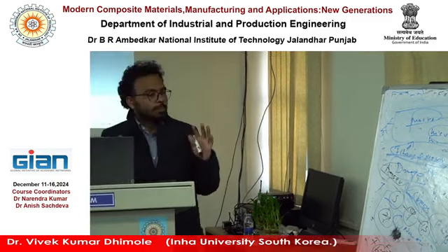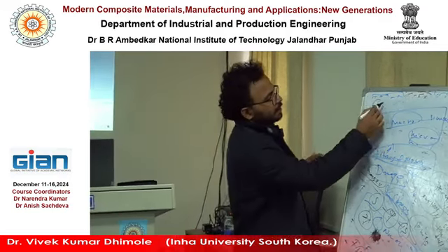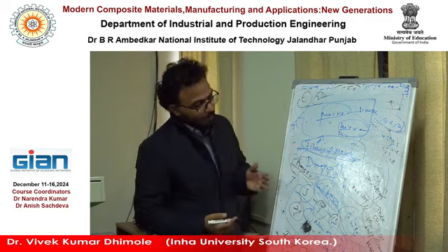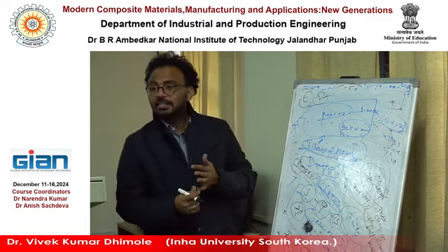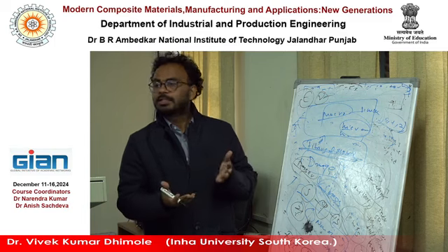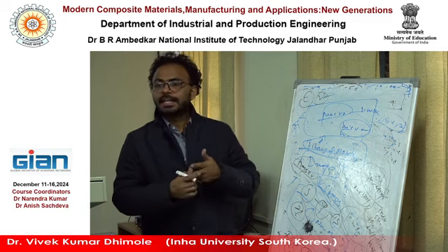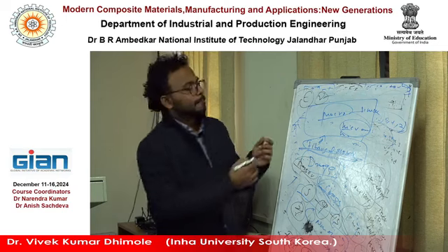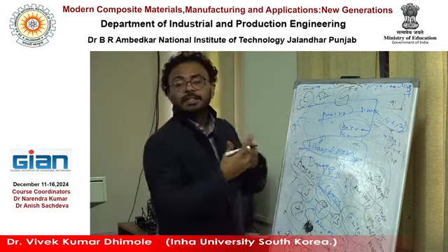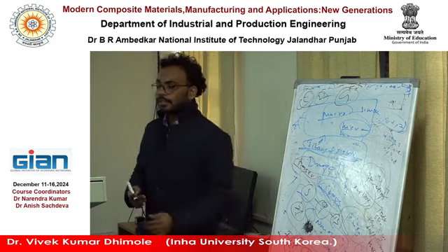Either isotropic, and isotropic needs just 2 things: Young's modulus and Poisson ratio. But when you have a composite, you have Ex, Ey, Ez, directional properties, right? Poisson's ratios in X, Y, Z, right? This is different. And shear moduli Gx, Gy, Gz. G is different, right? Shear modulus, each and everything you need for the composite one. Getting the point? Okay.